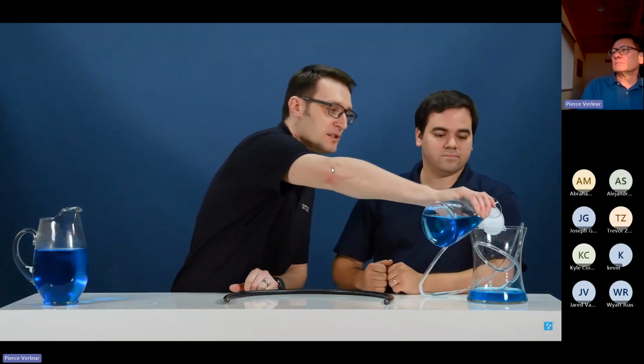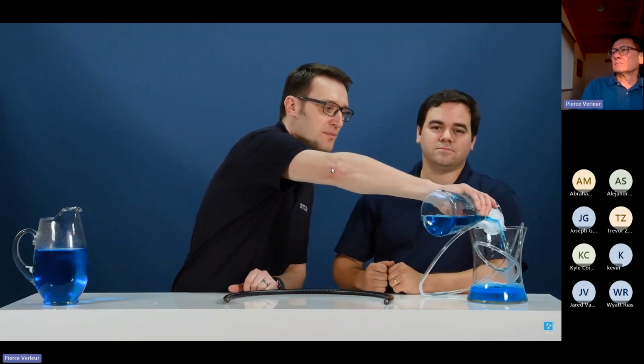Our XLPE insulation has been shown to be 4 times less charging current than a PVC nylon insulation. That saves you a lot of energy on your drive output. So that is basically taking the energy and putting it right to your motor. It drastically cuts down on the energy that you lose as heat and makes your drive system much more efficient.